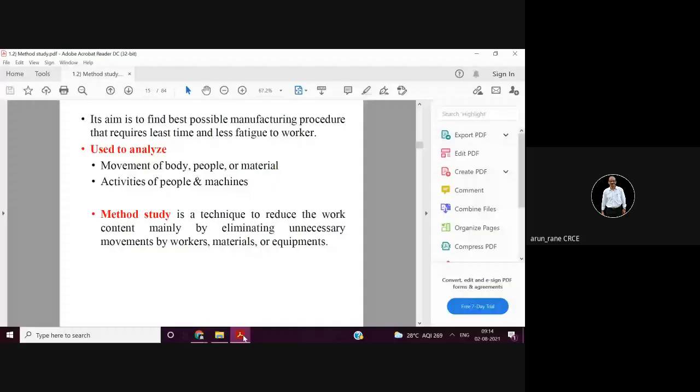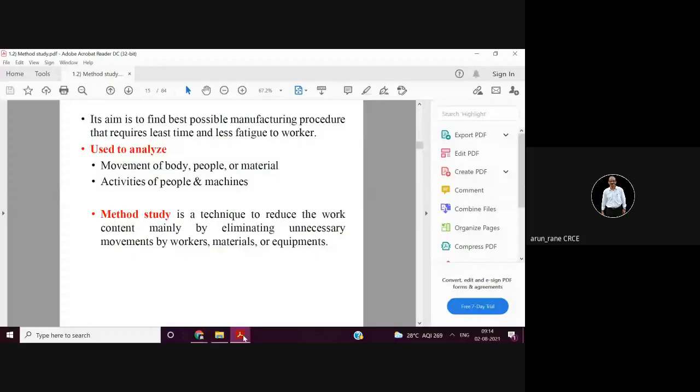But if the cycle time is more, what you can think is, you can add one more parallel activity at that workstation. You can have one more workstation there, so that the 5 minutes will be divided into 2.5 minutes. So like that, your line will be balanced.